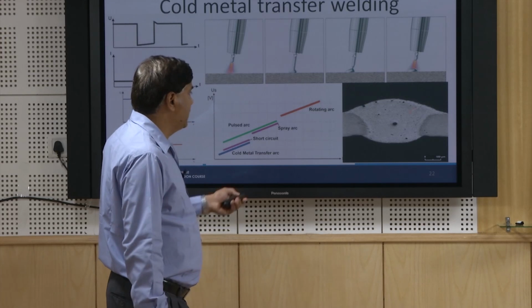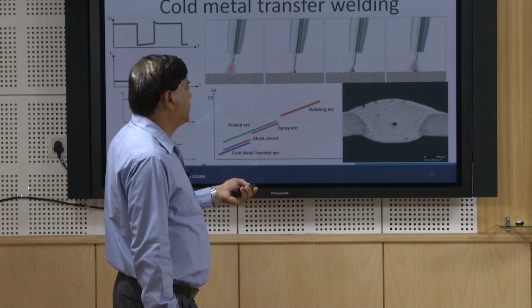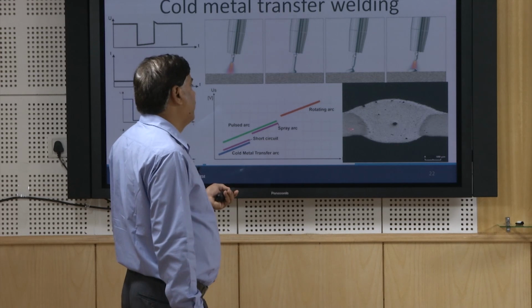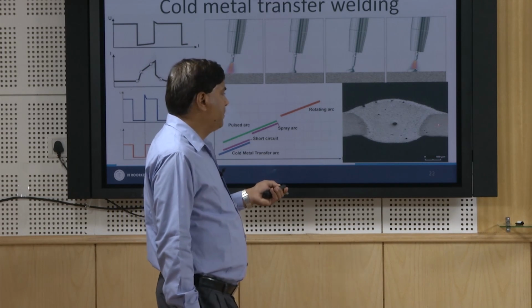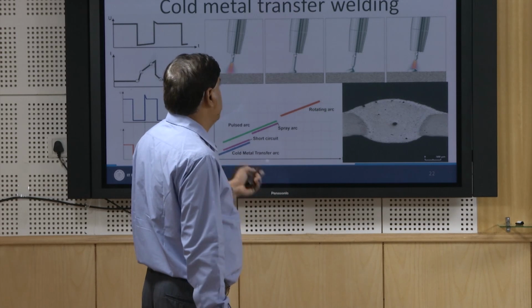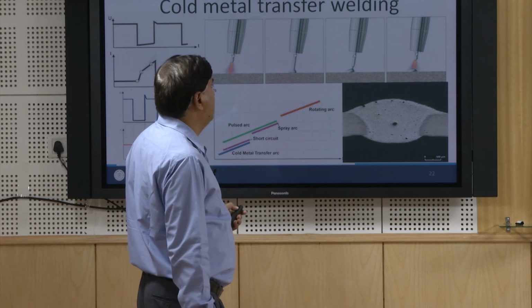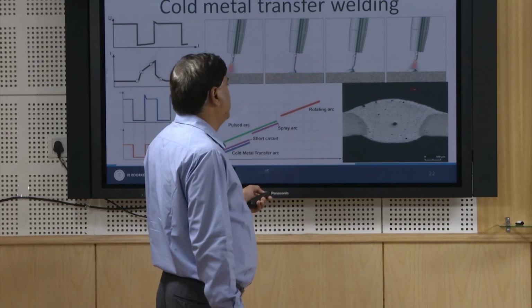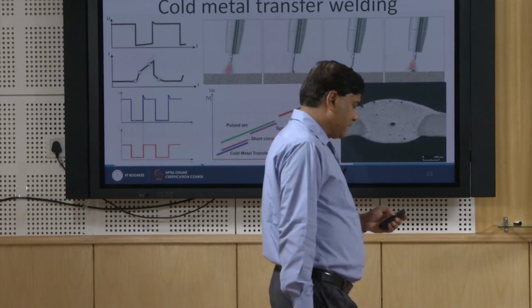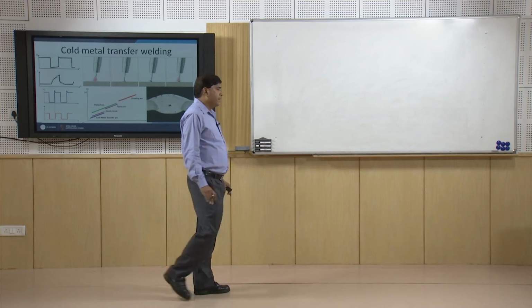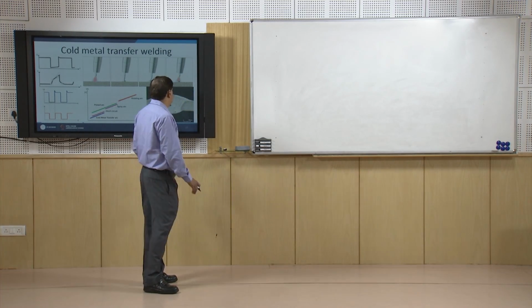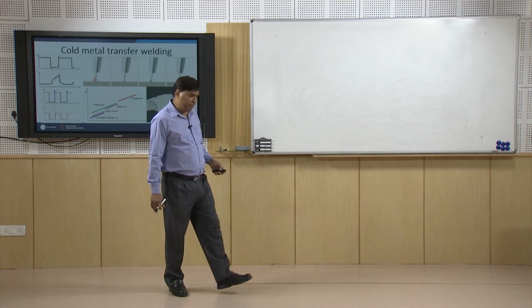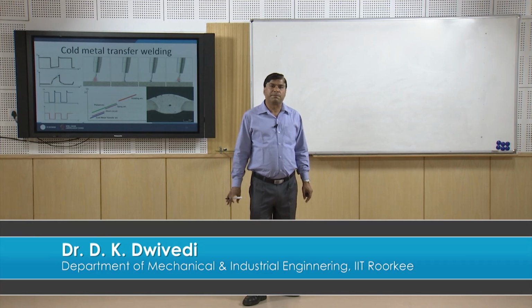That is what we can see here. This is a typical experiment which was used for developing joints of thin sheets, and the joint was made using the CMT process. However, it shows some pores and blowholes. The pores are of very small size, maybe 50 to 60 micrometers, and they are very isolated. Now we will conclude this presentation.